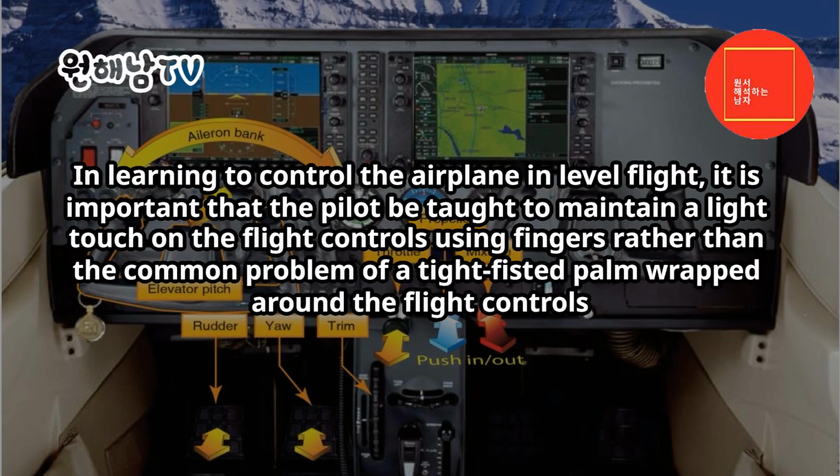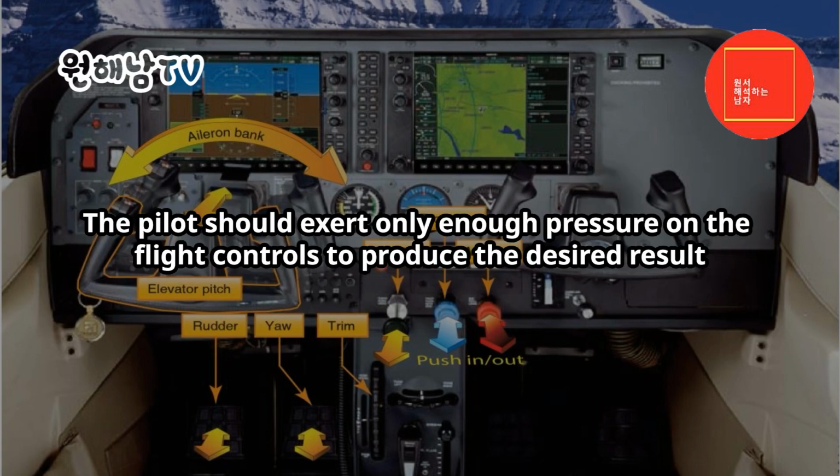Level flight. In learning to control the airplane in level flight, it is important that the pilot be taught to maintain a light touch on the flight controls using fingers, rather than the common problem of a tight-fisted palm wrapped around the flight controls. The pilot should exert only enough pressure on the flight controls to produce the desired result.